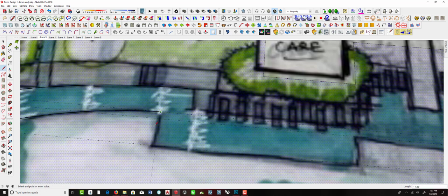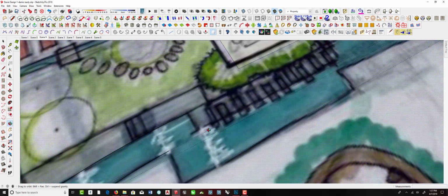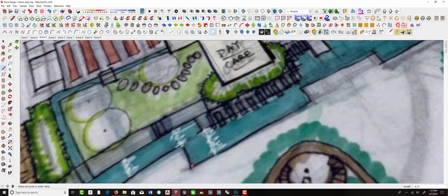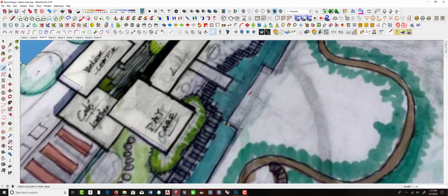All right, so now I'm going to switch to the line tool and come out here. Sometimes you'll find this alignment is very close to being on the main axes, but it isn't. So when I know that, I get perpendicular, hold the shift key down, and then snap to there, because I'm really trying to stay right along that line. Sometimes you're going to get that green axis, so even if I have to go the other way, hold the shift key down, snap it back to there.